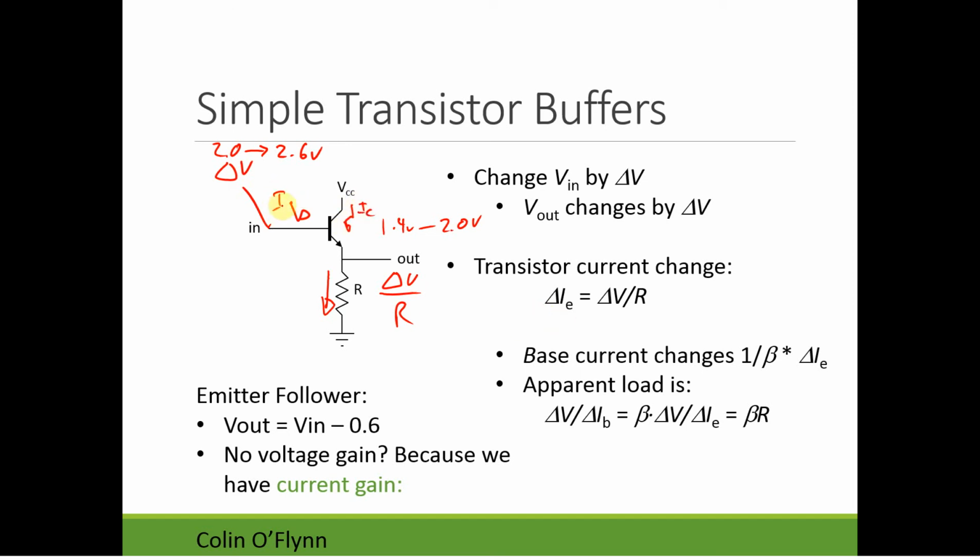The approximate relationship is that the collector current is this current gain figure beta multiplied by the base current. And this figure is normally quite large. So if we change the base current by 1 milliamp, the collector current changes by 100 milliamps or something.